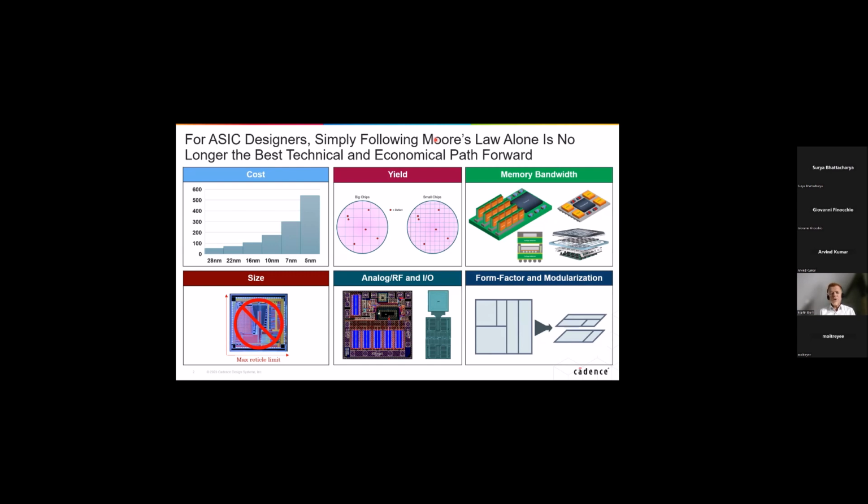There are more and more chips reaching the reticle limit, so you can't grow an SoC even further. That's a blocking point that people need to think about, having multiple chips in the same package. And as mentioned previously, going to advanced nodes is not always the best for certain applications like analog, or even the IOs, which even on advanced node chips are mostly analog circuitry, not best suited for the smaller nodes.